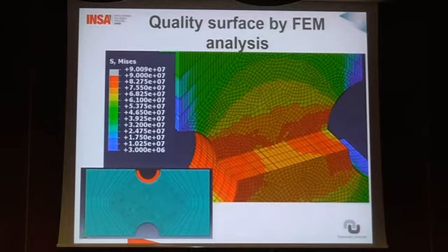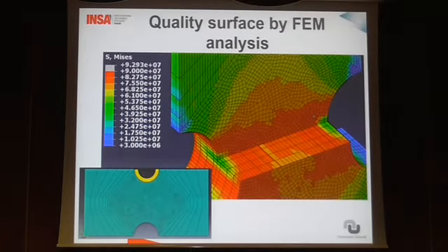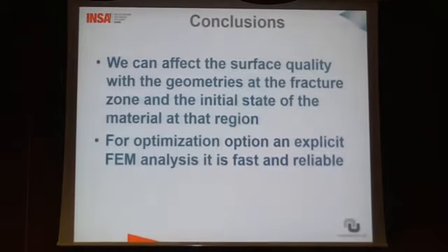But more interesting for the optimization will be the homogeneous shape in the positive distribution of the pressure. We have a distribution of stress that is quite homogeneous, especially here in the edges. But when we change the boundary condition to the negative condition, we can see near the edges the stress goes down. So that suggests that crack initiation is more inside the material than at the edge of the specimen.